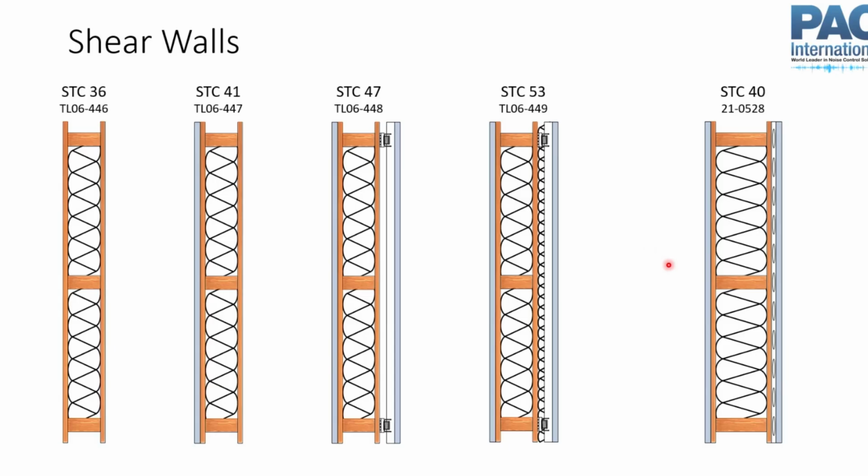If you think about a kitchen that's on a corridor wall, so it's kitchen wall and then the corridor, putting your sound isolation on the kitchen side creates an issue with hanging cabinets and all this kind of stuff. Now you could use acoustically isolated backers like we talked about, but that adds more detailing and specifications and things that you've got to pay attention to. So it complicates the design and construction of that kitchen.